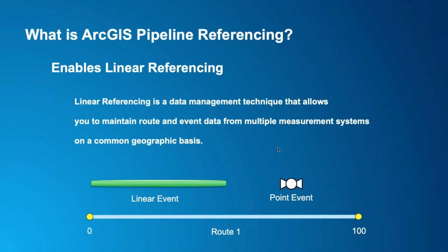And we put all these point and linear events in, reference those to that underlying route by their measure, so where they stop and start or where they live. And as the route manipulation happens, as the route is moved, those point and linear events stay glued to that underlying centerline, right? That's the primary driver of the linear referencing tools from a modeling technique.